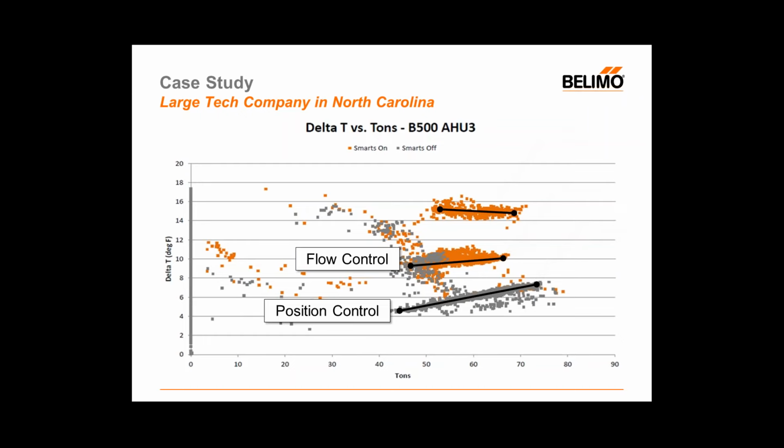The same valve, we then turned on delta T limiting, and we tinkered with it, and we figured out that we could get 15 degrees of delta T out of that coil and still create the loads required in the space. So again, the loads are in a slightly different range, but now we're getting 15 degrees of delta T. Let's go ahead and break that down to a specific load point, and that'll give us an idea of exactly what type of energy savings or resource savings we could employ here.